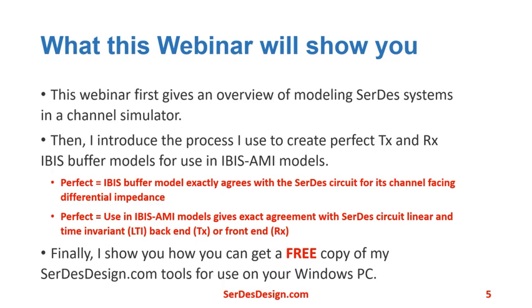What this webinar will show you. This webinar first gives an overview of modeling SerDes systems in a channel simulator. Then I introduce you to the process I use to create perfect IBIS buffer models for use in channel simulators. Perfect means that the IBIS buffer model exactly agrees with the SerDes circuit for the channel facing differential impedance.